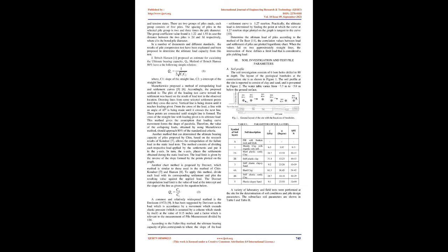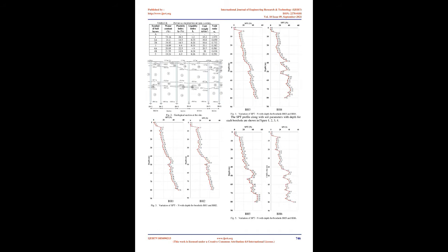Due to some limited conditions, in practice, it is usual to choose the maximum compressive load acting on the pile head about 1.5 to 2 times the design load in the test at the site. Therefore, in some cases, the pile static compressive test has not given the ultimate bearing capacity of piles. Mazurkiewicz, Chin-Kondner, and Decourt have proposed graphical methods based on the correlation between compressive load and pile displacement to predict the ultimate bearing capacity of piles.